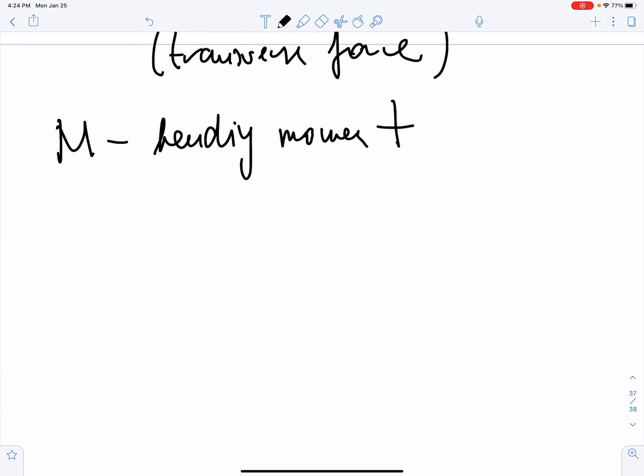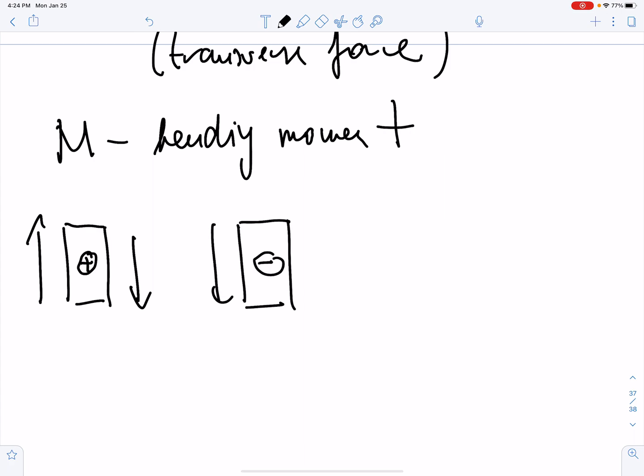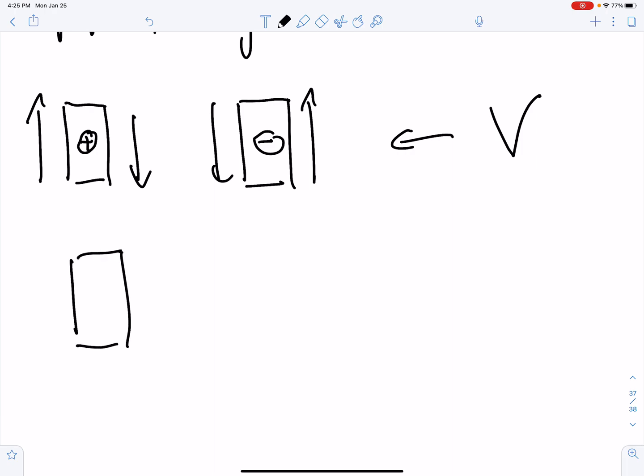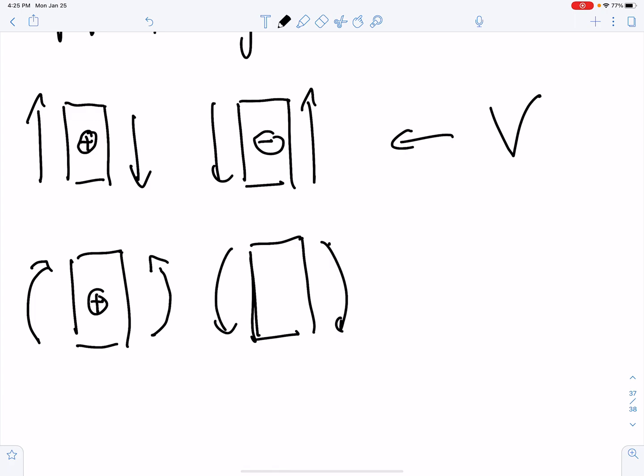And again, this is probably something you've seen in 310, you adopt a certain sign convention. If we're looking at the infinitesimal piece of the beam, a situation like this gives positive shear, and a situation like this gives negative shear. As far as bending moments are concerned, we're dealing with two dimensions here. A moment that creates a convex curve is a positive moment, and a moment that creates concavity is a negative moment. So this is the nomenclature that we'll be using going forward.